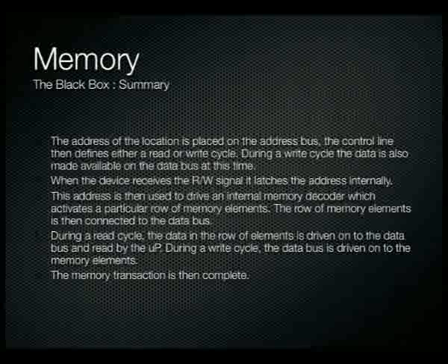Okay, so basically once the memory device has read those values on a write cycle and driven them onto the memory elements, the transaction's over. Same thing when we're doing a read. Once that value is driven onto the data bus and the microprocessor has read it, the transaction is over. Generally this has to happen within a certain period of time, so there'll be a certain number of clock cycles.